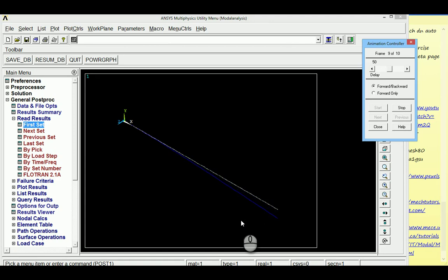In this case, it is 8.13. So when it is excited to 8.13 hertz, then the member behaves like this. So this is the mode shape. So you need to plot this shape. So at maximum moments, you can just write the sketch showing the uppermost and lowermost position of the member. You can show in a sketch, and that will be the mode shape. So this is the first mode.